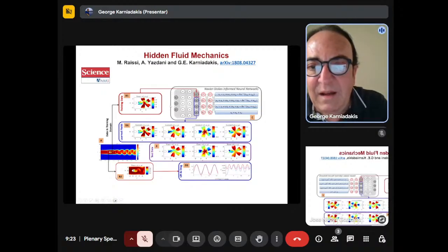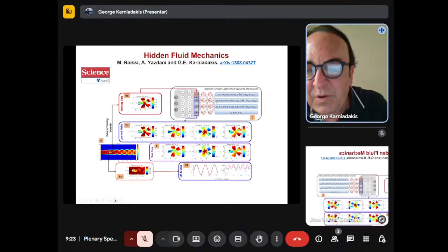So what we have, in addition to the governing equations for the U and the V velocity and the mass conservation, is this first equation, I don't know if you can see on the right here on the top, E1, which is basically the conservation of a passive scalar, the convection-diffusion equation for the scalar.